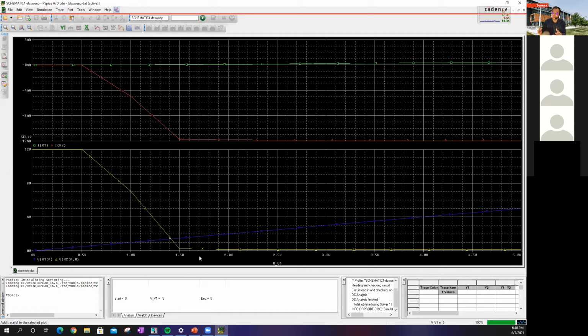When you implement this in the real world, or when you have a job in this kind of field, you'll see which logic you want to use. When you use CMOS, which is more tight, 0 to 3.3, or you want to use TTL, because sometimes the cutoff point is a little bit further than 3.3 volts, right?